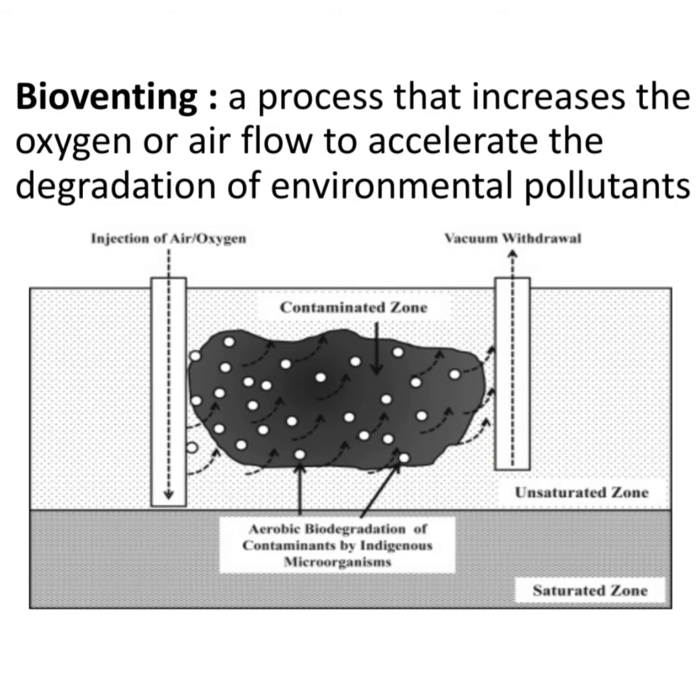A process that increases the oxygen of airflow to accelerate the degradation of environmental pollutants. Here in this image you can see that injection of air or oxygen is done into the soil and there is aerobic degradation of contaminants by the indigenous microorganisms and the contaminated zone is removed by vacuum withdrawal.